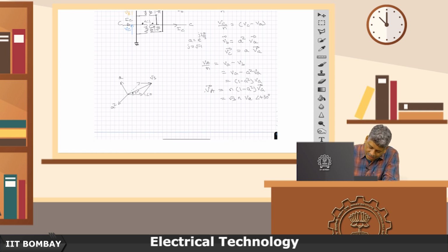So, this basically means N is implicit here. What it means is, because any voltage is always, if nothing is said about a terminal and I say this voltage, then what is the reference? It is with respect to neutral, which is again under ideal conditions at the ground potential, which is a balanced condition, it is also at the ground potential, which is at 0 value.